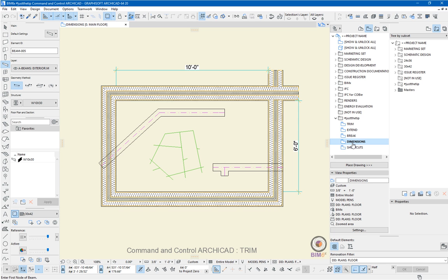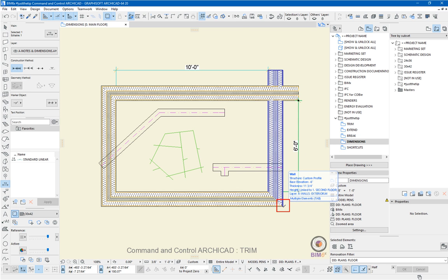The next one to look at is how we can use the control key with dimensions. So in here you can see I've done a fair bit of messing around. This is the trim exercise I used earlier. I have a couple of dimension lines in place, and like the other options other than trim, if I want to edit a dimension, make sure the dimension line's active. So I can select this, and maybe what I want to do is add the corners. So we're going to hold down control, look for a tick mark, make sure we've got highlight so it's going to associate, click the mouse, and there we go, control click, and that's just added